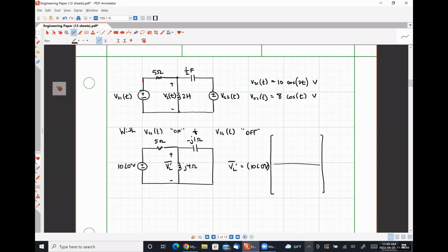So the impedance of the capacitor is 1 over J times omega, which is 2, times C, which is 1/2. So that's literally 1 over J1, which is the exact same thing as negative J. Okay. Yeah. All right, so applying voltage division correctly, thank you for pointing that out. Just total brain fart there.